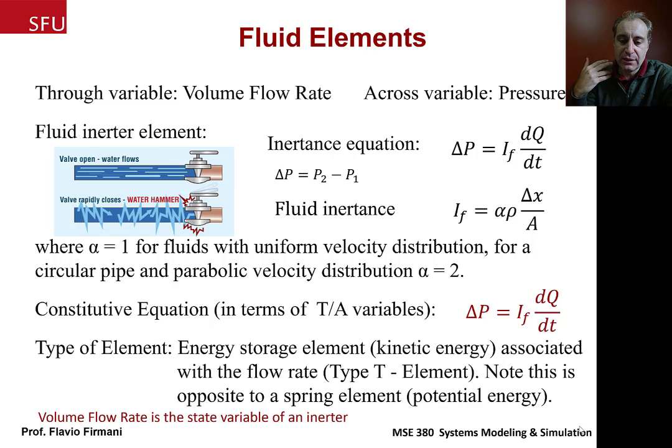And when there is a sudden change of the flow, then that inertia will compact the air, and it will increase the pressure in that trapped air inside the pipes.